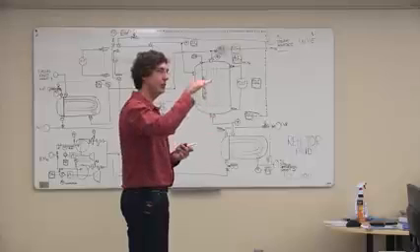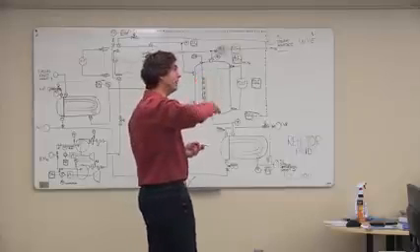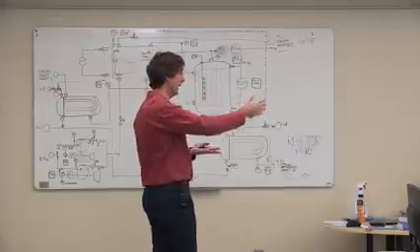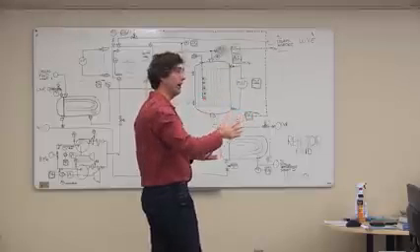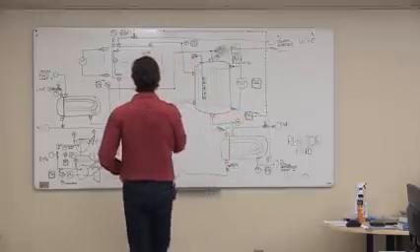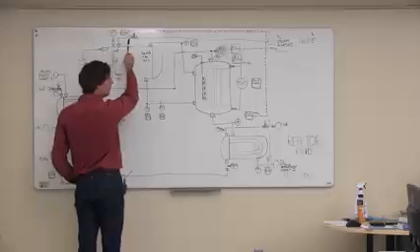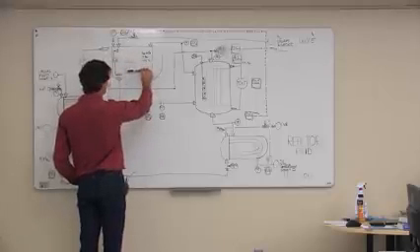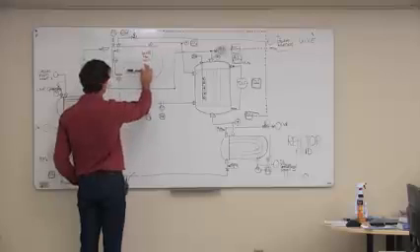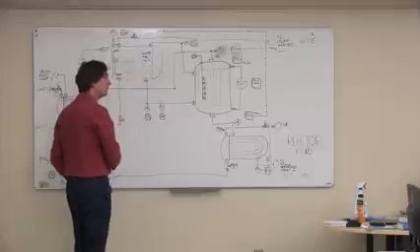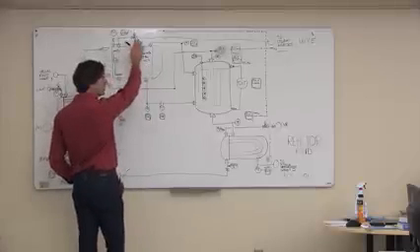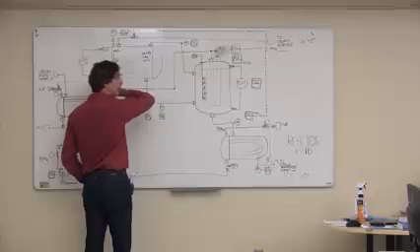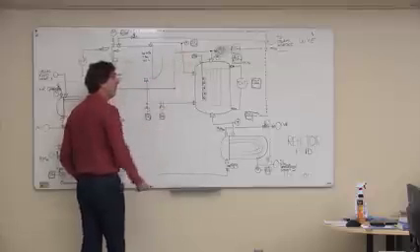The level starts to rise sometimes for a little while, and then the level starts to drop again. It's like a dynamic thing, right? If we start to open or close that valve right there, we could expect that if we drop the pressure a little too quickly, the level might rise a little bit, and then start to drop. It drops because as you drop the pressure, we actually boil more steam right out of the steam drum.